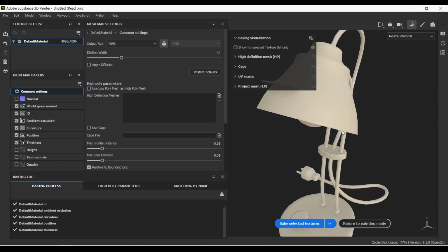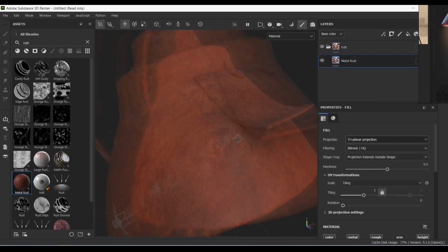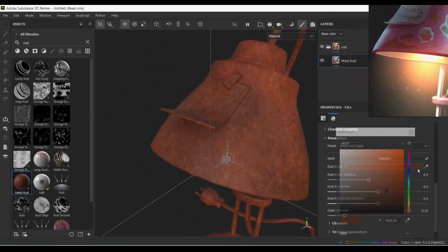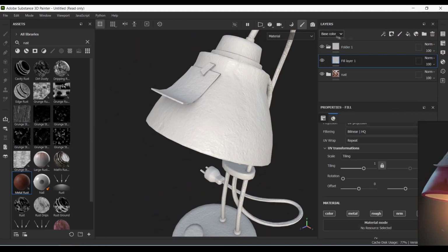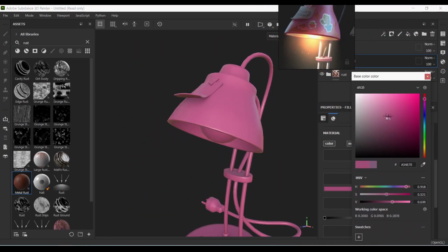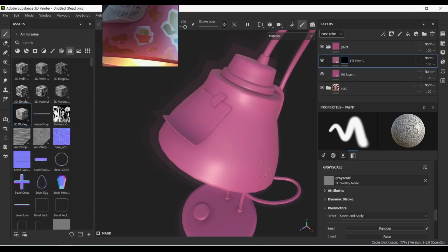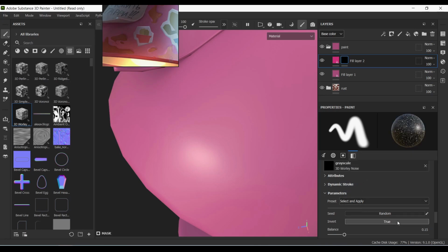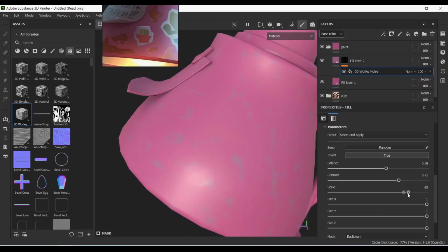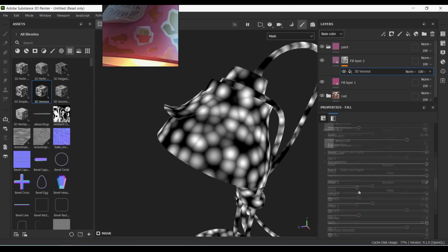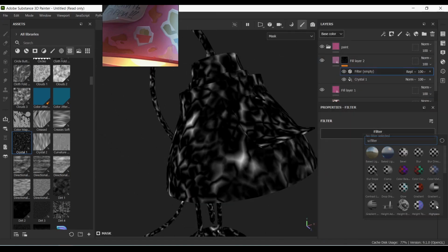The longest stage of model creation for me is texturing. In general, this is pure art and experimentation along with experience. What about important things? I would advise you to learn anchor points and masks, as well as blending modes. At the beginner stages, in general, everything can be textured with ready-made smart materials. The main thing is not to forget to bake texture maps in texture set settings.